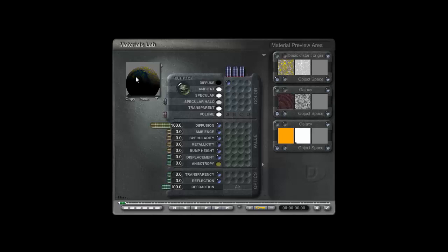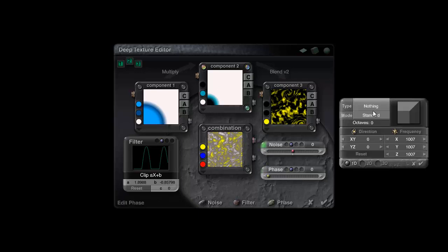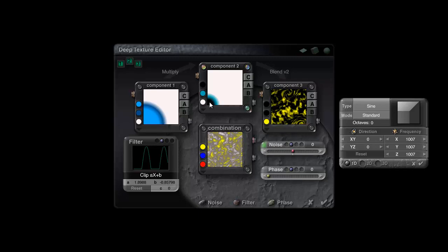However, you can see the problem here, that this area is moved off, which is why we need to move this. We can move this, it's nice and symmetrical, using the phase function again. So we select the sine, see if it's going to move far enough. It'll depend on the scale, and then, right, okay, we need to set this frequency down to 0, don't forget that step. And then give it the sine, and it shoots off to the left. But bear in mind, with this noise function, we could rotate it round 180 degrees, and then I can move it across to the right.